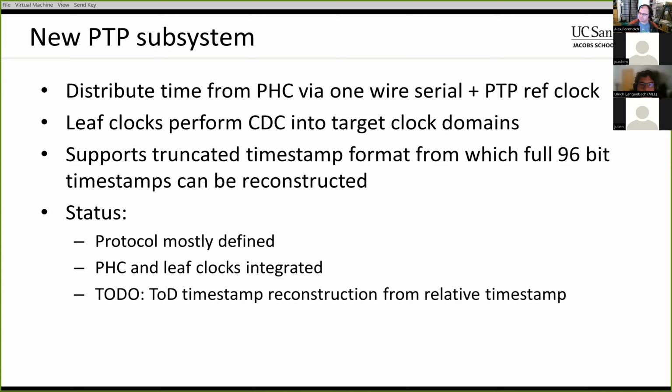But there are potentially some gotchas on that front, so I figured I'll go ahead and get the current thing integrated and make sure everything works well there, and then bring in this newer setup to save some more logic resources once the core parts are working. So that's going to be the next thing that I'm working on on the PTP side of things. But the main thing at this point is I have a lot of the module level interfaces updated to have the time distribution serial signal added and the old timestamp signals removed or otherwise updated. All right, so that's that.